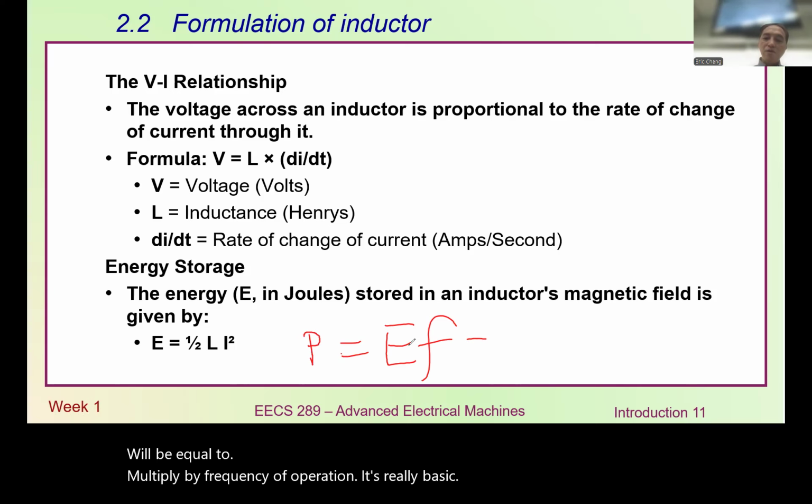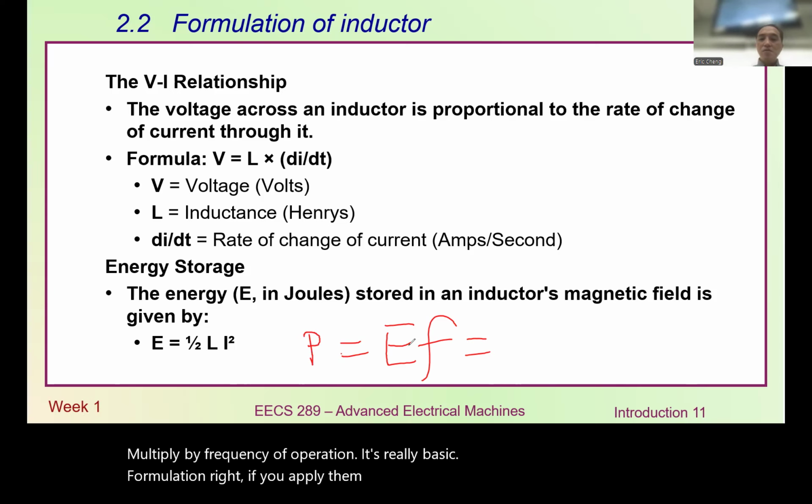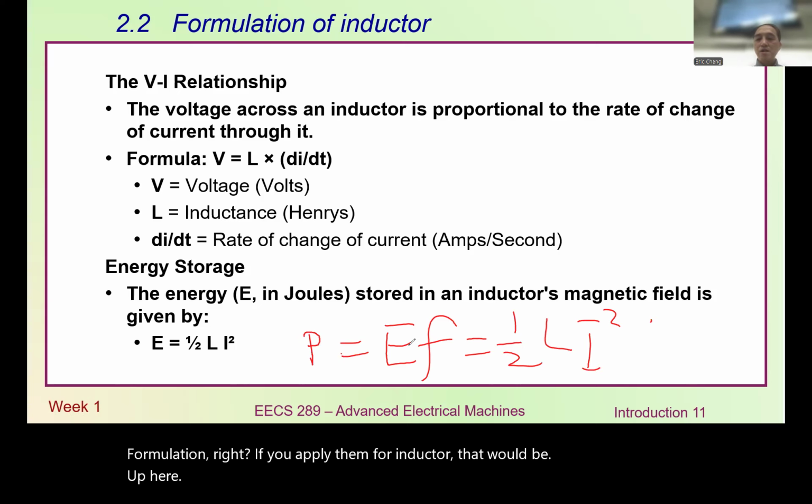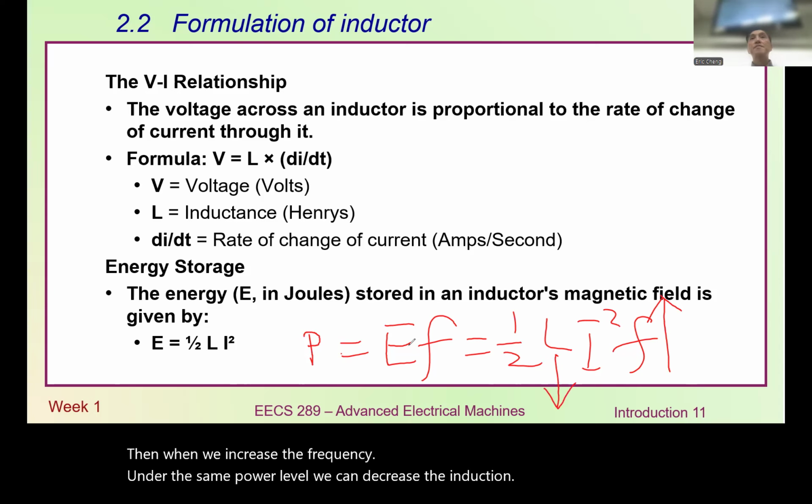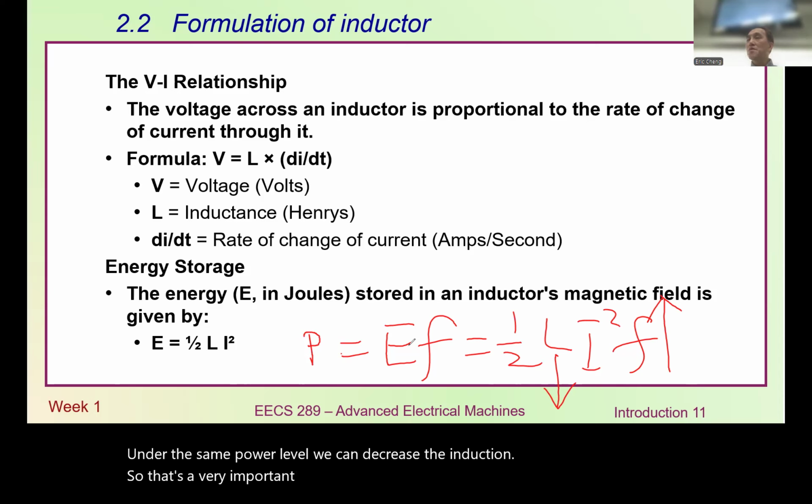If you apply it to an inductor, that will be half L i squared times frequency. So for a motor or whatever we tend to use, if we want to fix the power flow, then when we increase the frequency, under the same power level, we can decrease the inductance. That's a really important phenomenon for any motor or energy storage system.